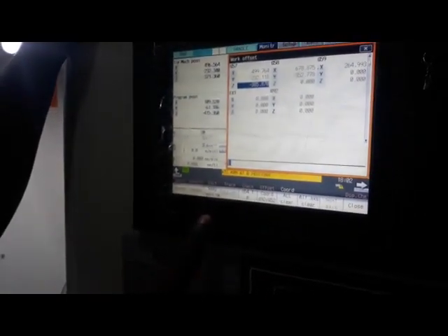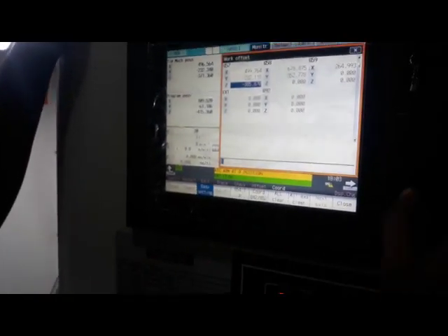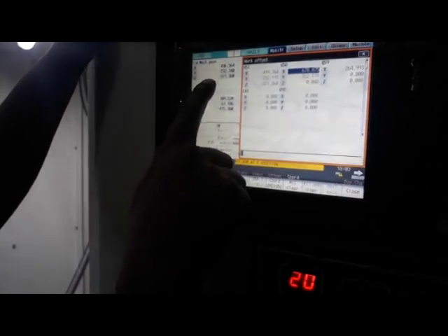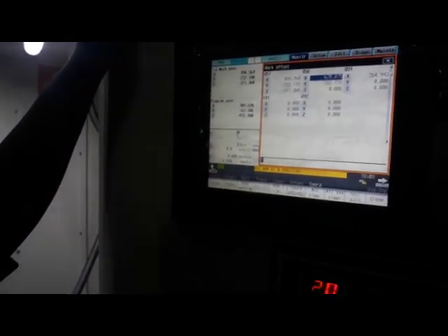So here in setup or in monitor, click the coordinates. In G57 I need to replace the position, which was the position for the 10 flat end mill. How I'm going to do it is by clicking on easy setting. I'm going to click on yes. So I've got a new value in here, -37.360, and that's the position of the machine at the moment.